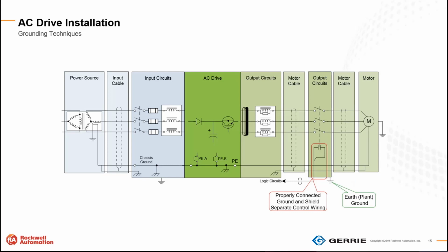So what we're saying is that we can tie the two grounds together at some point in that box on a common little ground bus, or some way to tie them directly together, not relying on the box as a conductor. That is always a good practice. We're finding that as well.